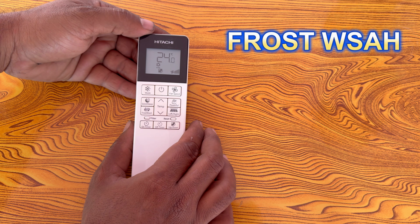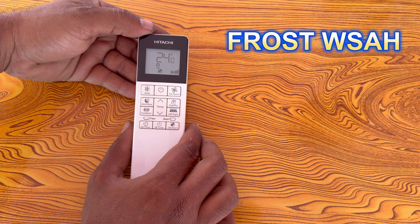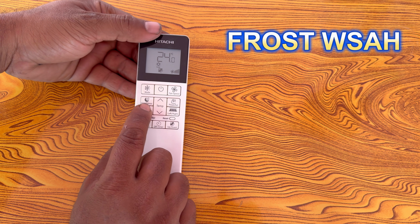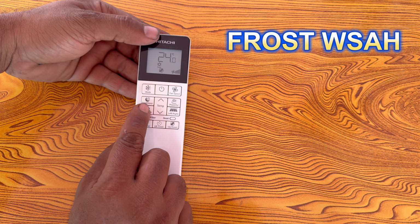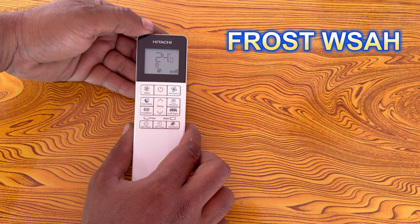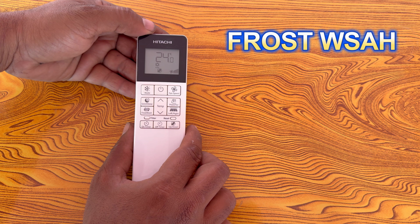The next button is frost wash. This Hitachi model doesn't have a frost wash function, but I'll explain this function in detail. After pressing the frost wash button, whenever you turn the AC off after using it, it will continue to run for 1 hour. The moisture in the indoor unit's coils will dry out, and the dust will be flushed out with water through the drain assembly. During this function, you cannot use the AC for 1 hour.